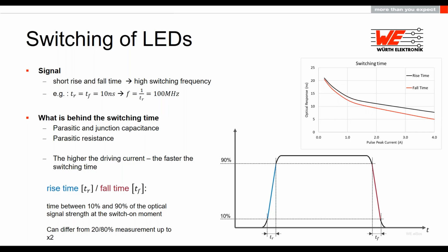If you remember, this is why we use a gold contact, because we can have a lot better solderability on the PCB and thus reduce some of the parasitic resistance that we bring into our designs or schematics. Another way to reduce the switching time is the capacitance. We use pre-selected chips and dies with a low capacitance so that we can have very low switching times.